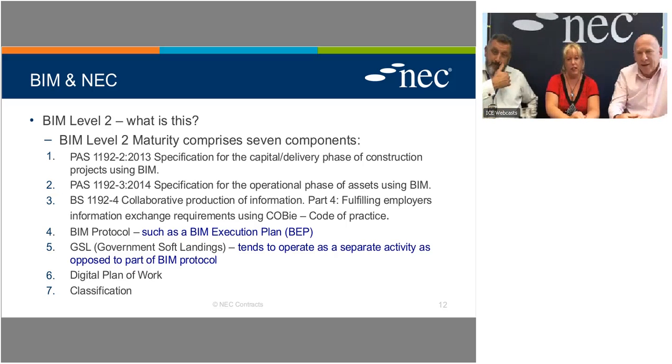The only point I want to make on this slide is to talk about the BIM protocol. The question that Rob and I discussed yesterday was how do we take something like a directive for BIM and align it within the NEC contract. The easiest and sensible way is to develop a standardised BIM protocol. I've seen that work with varying levels of success and detail across major frameworks. Nothing particularly brilliant at the moment, but the best are those prescribing a BIM execution plan, which lays out areas such as design competency assessment, levels of approvals and dates for approvals, use of COBie, and what the platform is going to be.